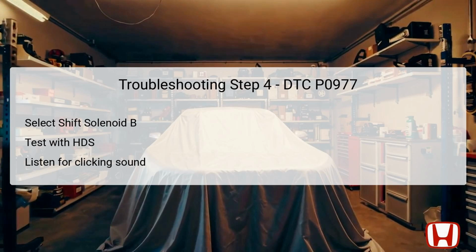A clicking sound indicates that the solenoid is receiving commands from the PCM and is attempting to engage. If the clicking is heard, this signifies that at least some communication is happening between the solenoid and the PCM, and you'll proceed with further diagnostic steps.